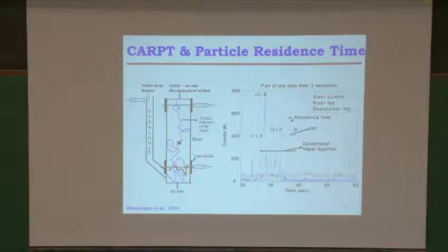The time that the particle spends outside of the closed system does not count toward the true RTD. The time that is spent in the system is between A and B, and between C and D. That is what we call the first passage time distribution: the actual time that the particle spent in this region during its first passage through the system. Now, if one was doing this with a conventional tracer approach, you would think that the RTD was based on the time that the particle spent between points A and D. The fact is, that's not correct. It's actually the time spent between A and B, and also C and D.